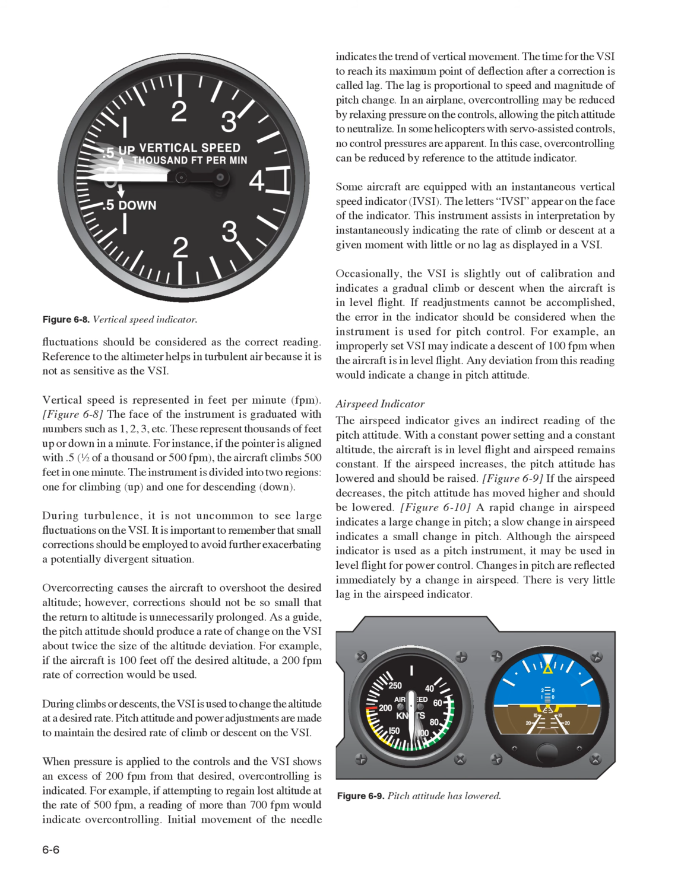In some helicopters with servo-assisted controls, no control pressures are apparent. In this case, overcontrolling can be reduced by reference to the attitude indicator. Some aircraft are equipped with an instantaneous vertical speed indicator, IVSI. The letters IVSI appear on the face of the indicator. This instrument assists in interpretation by instantaneously indicating the rate of climb or descent at a given moment with little or no lag as displayed in a VSI.